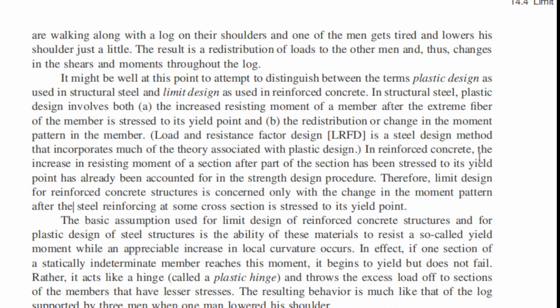Therefore, limit design for reinforced concrete structure is concerned only with the change in the moment pattern after the steel reinforcement at some cross-section is stressed to its yield point. So when we are talking of plastic region, the reaction of steel and reinforced concrete will differ in this particular manner as described.